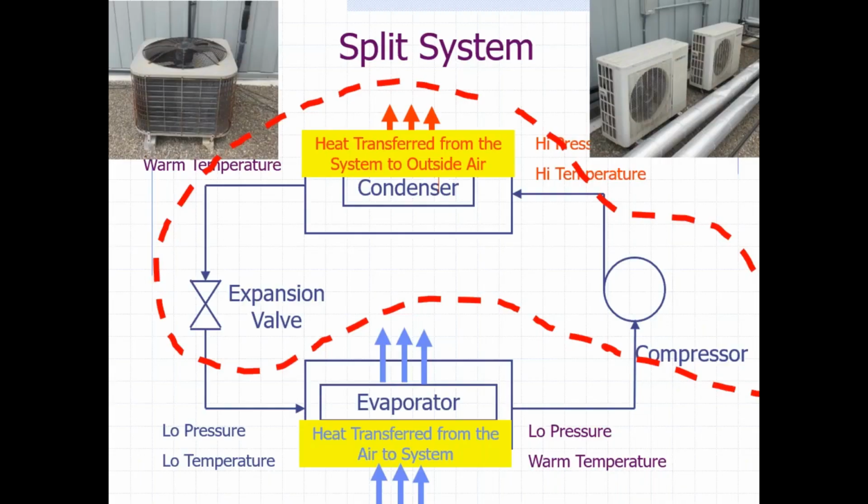Okay, I realized I had missed this. Split systems. So split systems use the same whole thing, but they're different than package units. Package units deliver chilled and cool air or hot air to parts of the building. A split system doesn't deliver any air. It delivers cool refrigerant, okay? And I don't have a picture of the other part, the evaporator part, but inside the building somewhere, there's just a fan, which just provides cooling. And so it has the coils in the evaporator.